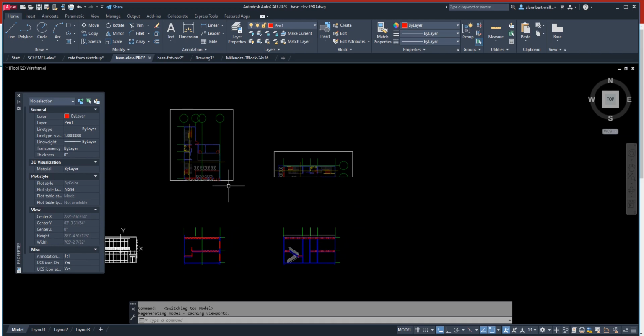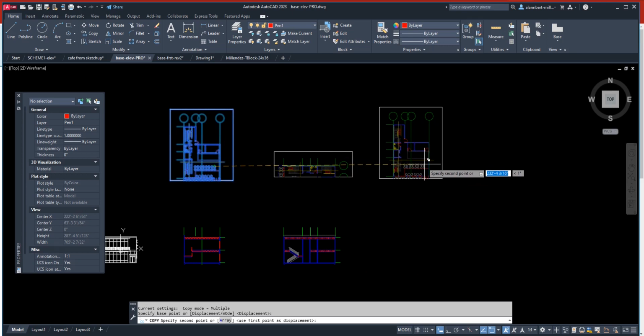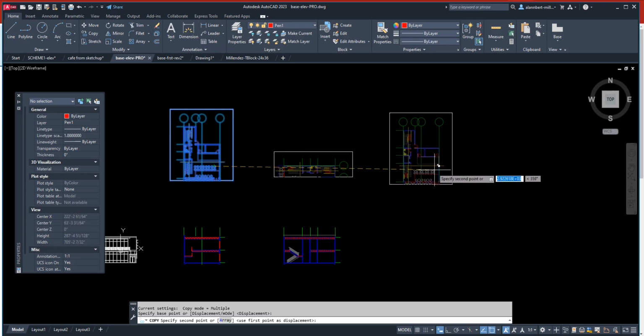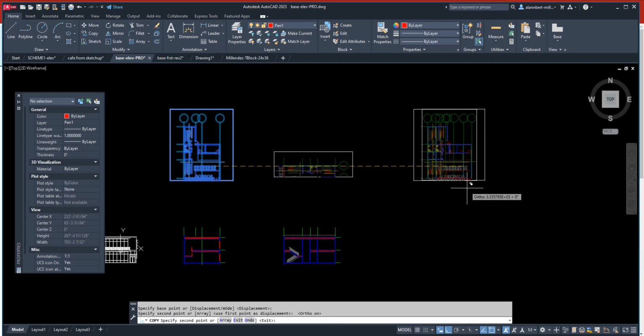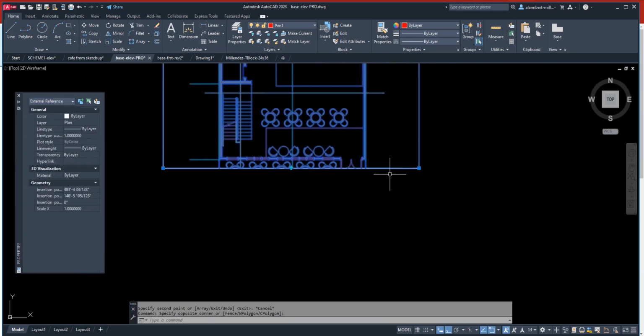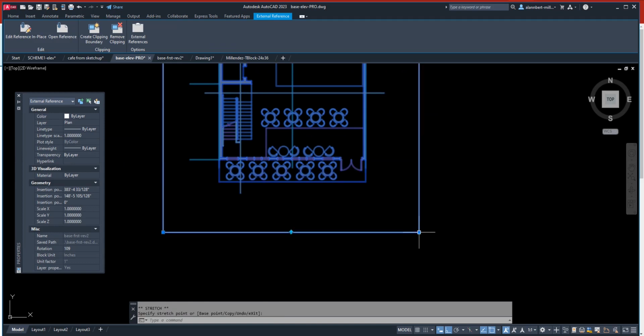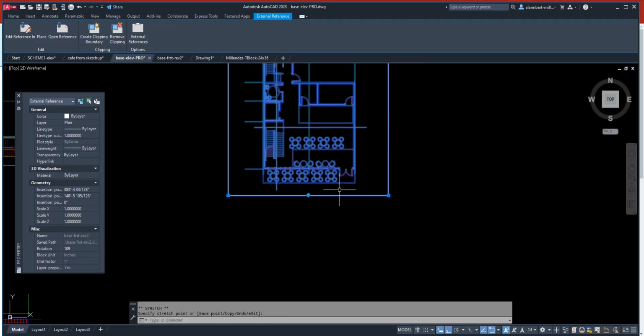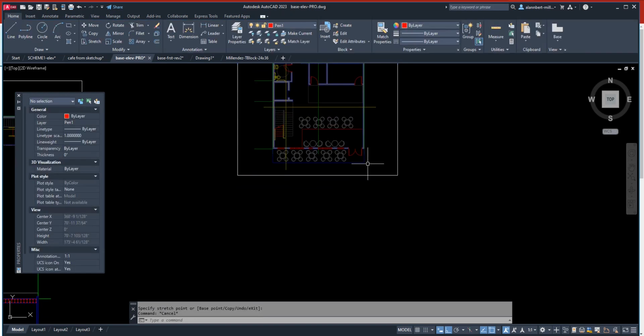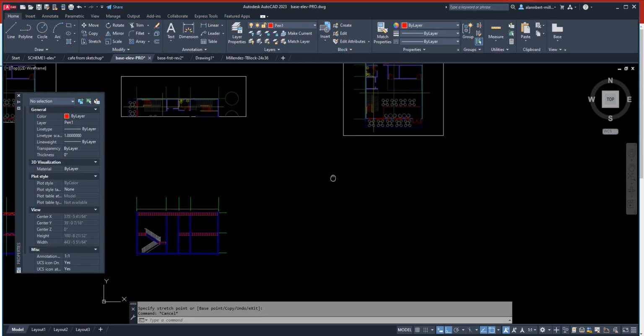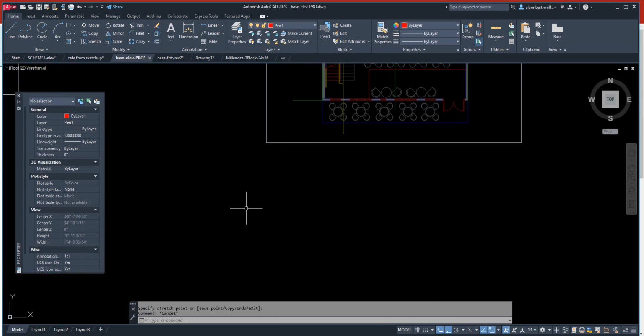We're going to now move this aside, or you can copy. Let's just copy so that we know that everything is in the correct spot. So we're going to copy this base plan. Let me just make sure it's straight. There you go. And we wanted to adjust the clip box so we can see the whole front, right? There you go. And then just like the process of doing sections, we're going to draw a line and find the extents of the building.